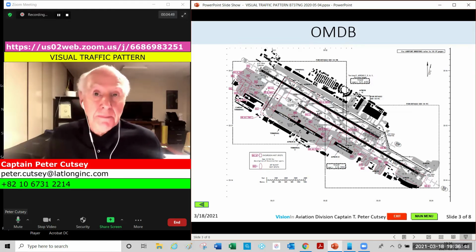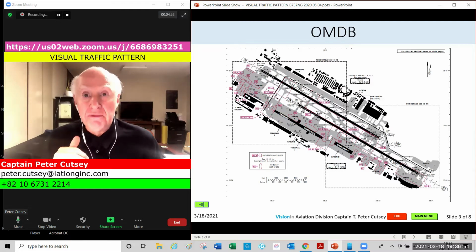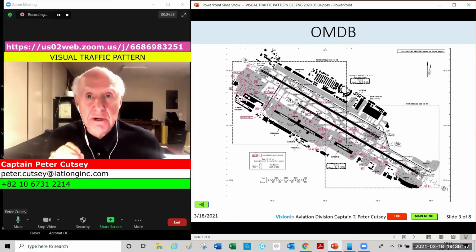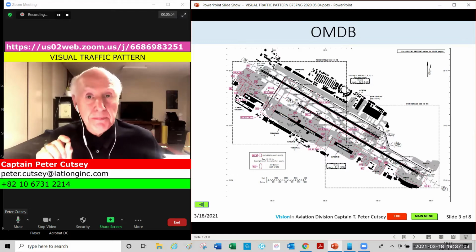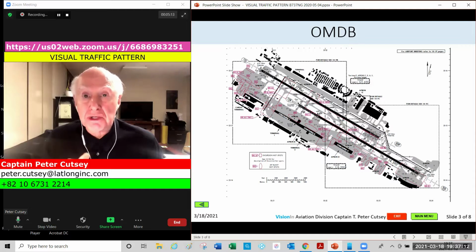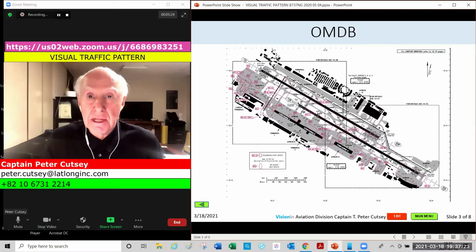So we're going to be using an altitude rounded above 65 up to the nearest 100. So it'll be 100 plus 1500, which is the height above ground for a traffic pattern. So on the MCP in the altitude window, we're going to set 1600. And as a reminder, on final approach to be established on the centerline by 500 feet, we'll set our baro minimum to 565, which is 500 feet above airport elevation. Keep that in mind, and the instructor will have you set up the nav display.